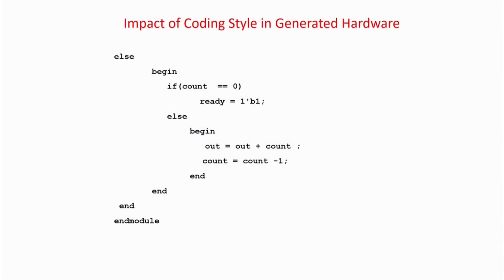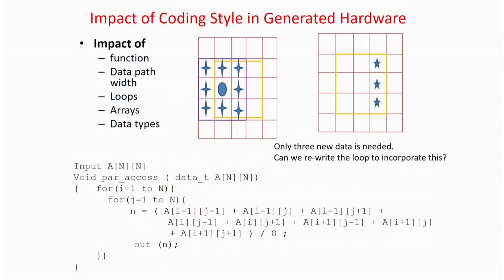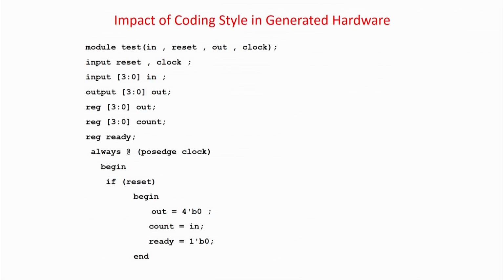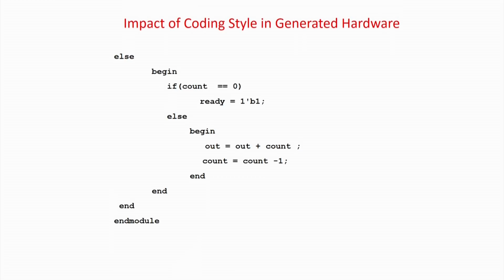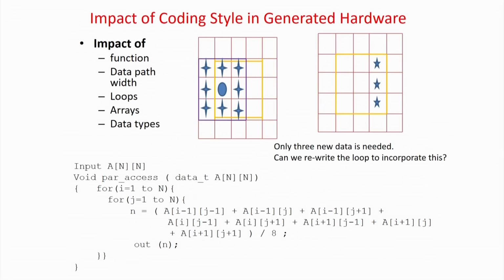This is just a very low level diagram for this hardware, and you can see that if you are using a counter, then if count is equal to 0, this is a down counter. So here I am freezing it. This Verilog implementation will be cheaper because it checks if count equals 0 instead of n. If I go for n checking, this will be a larger circuit, because checking count with n involves a lot of XOR gates, but count with 0 is a simple AND gate.